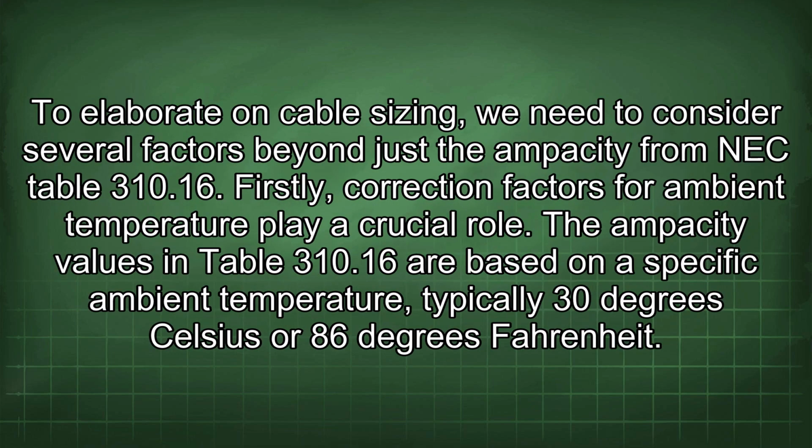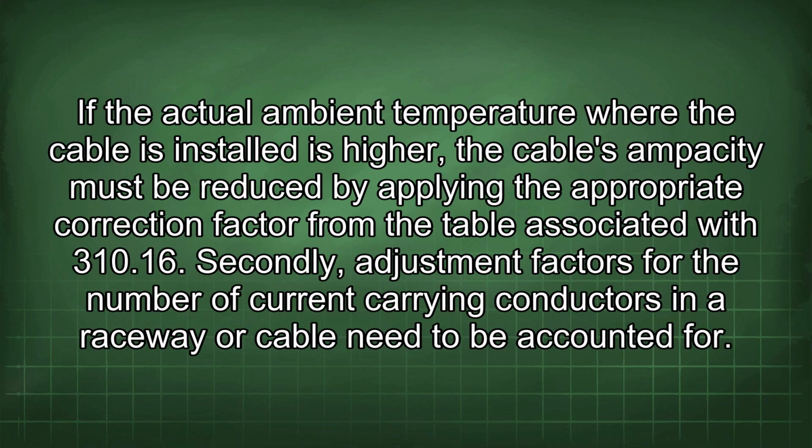To elaborate on cable sizing, we need to consider several factors beyond just the ampacity from NEC Table 310.16. Firstly, correction factors for ambient temperature play a crucial role. The ampacity values in Table 310.16 are based on a specific ambient temperature, typically 30 degrees Celsius or 86 degrees Fahrenheit. If the actual ambient temperature where the cable is installed is higher, the cable's ampacity must be reduced by applying the appropriate correction factor from the table associated with 310.16.